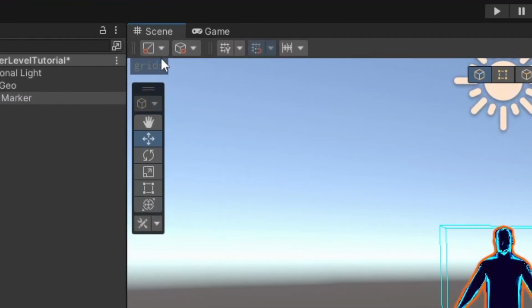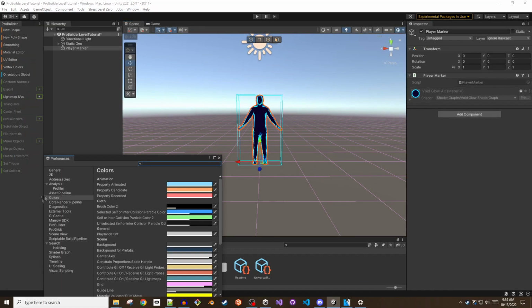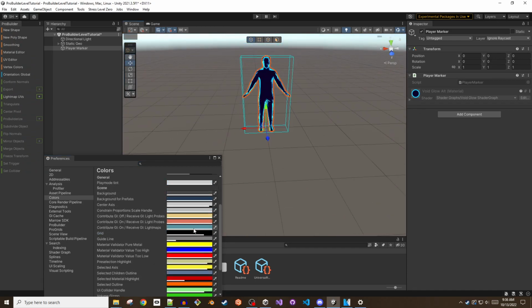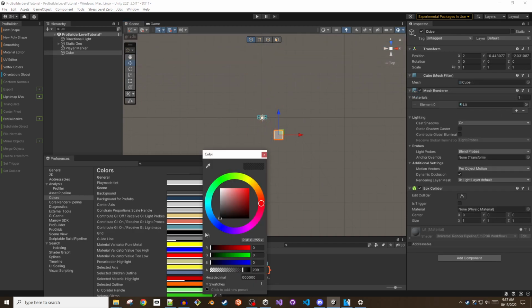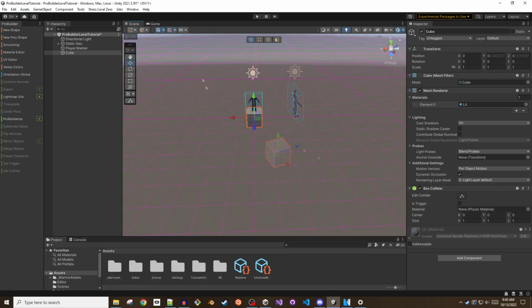One of my gripes with the Unity Grid tool is that grid snapping is only available when the handle tool is in global mode. If you try to manipulate an object in local mode, the object will not snap to the grid as it is moved or scaled. Second, the grid visuals are monochrome, and the default color is hard to spot against similar colors. This is remedied easily enough by setting the grid to something with high contrast like magenta. However, the default grid is only visible in a single plane, and the finer increments between main units nearly disappear if you move the camera too far away from the selected object.